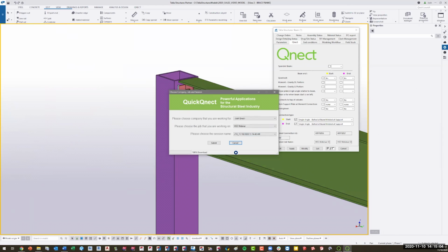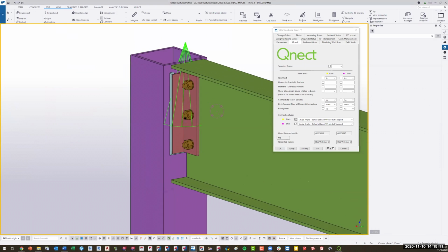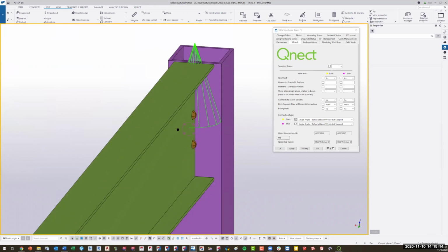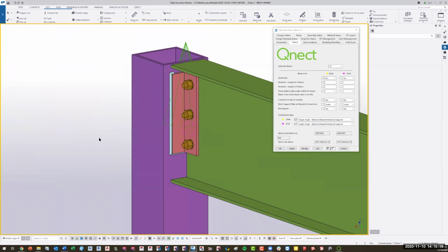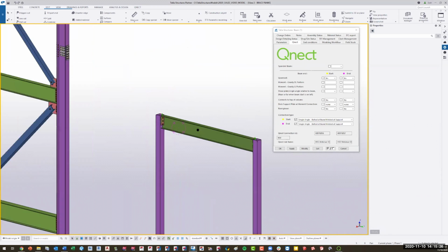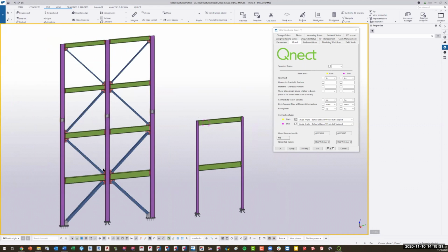And now going from a shear plate to a shear plate with less bolts to a double angle knife connection, now to a single angle, still with those less bolts. In fact, the weld volume or length is probably roughly around 40 to 45% less than a shear plate because of the nature of the double-sided weld at the shear plate. So that's a lot of the HSS style connections and how to go about adjusting those and getting the most bang for your buck.